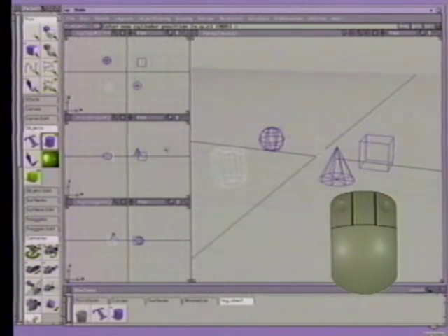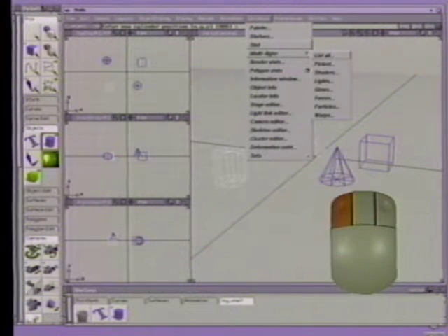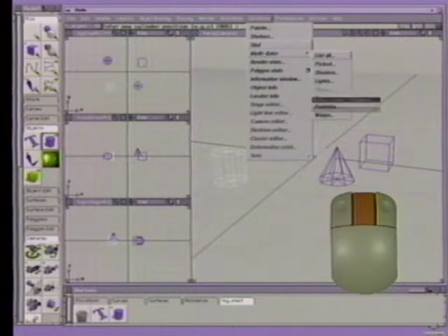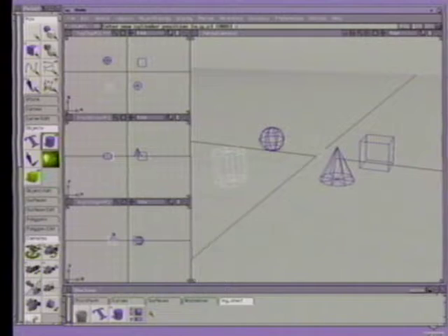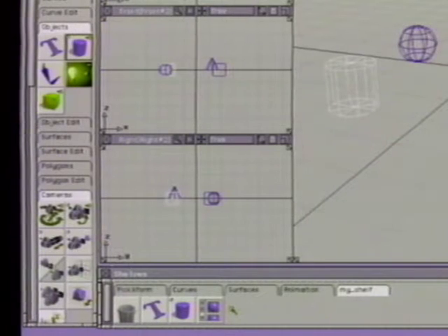Click on the Windows menu to post this menu. Click on the Multi-Lister submenu to post it. With the middle mouse button, click and hold on the Shaders menu item. Drag the name box down to the shelf and release. Now the menu item is shown on the shelf, since you can add both tools and menu items to your tool shelf. Once you have several tools on a particular shelf, you may want to reorganize their position.